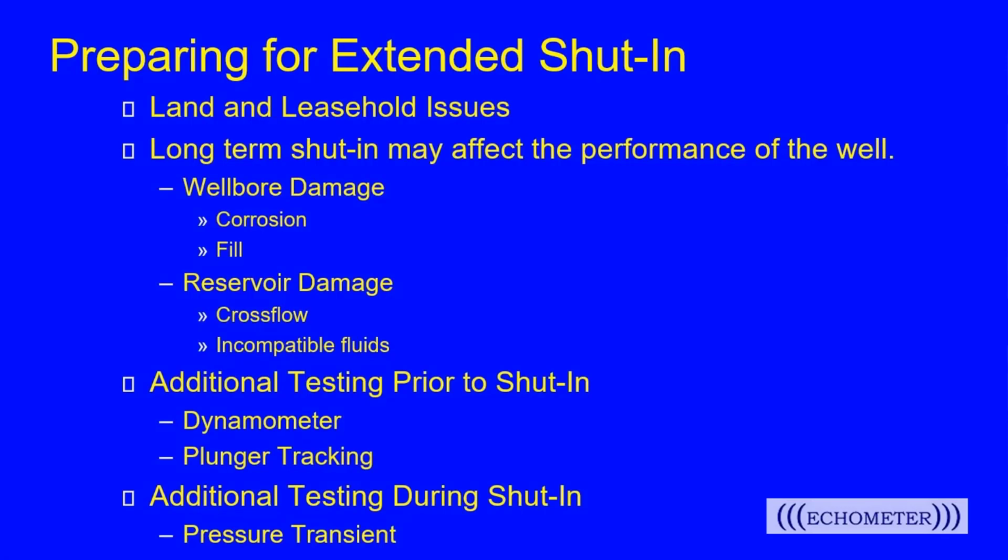But as you shut the well in and the bottom hole pressure increases and one zone's pressured higher than the other, the pressure in the wellbore may increase towards the pressure of the higher zone, and it flows into the lower pressure zone. And that cross flow may contaminate the other zone, bring in some incompatible fluids, cause some formation damage, and so on.